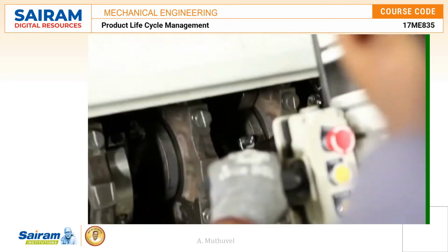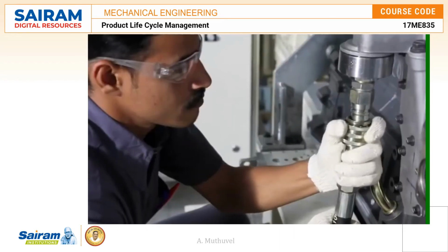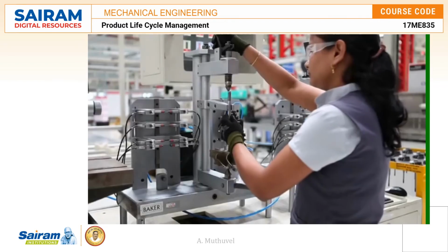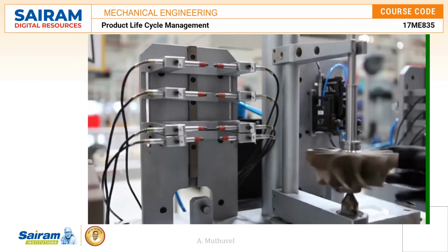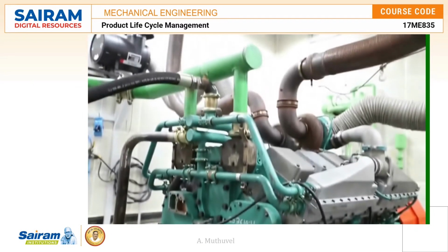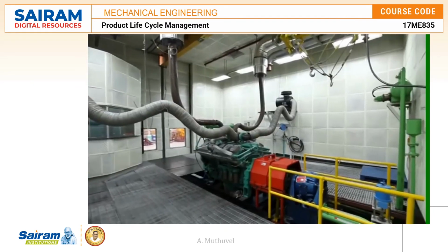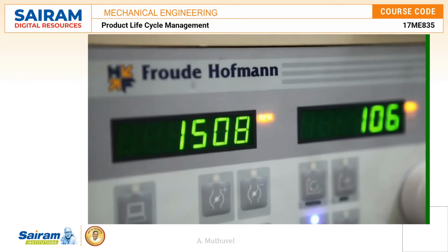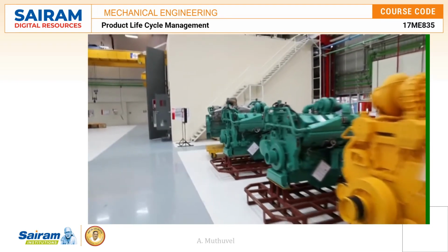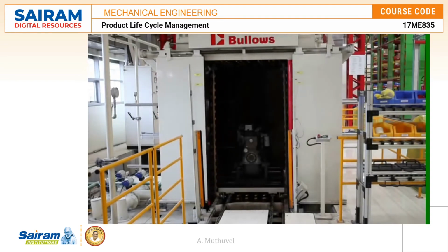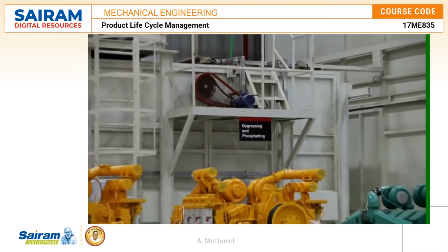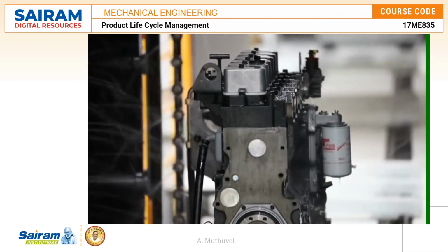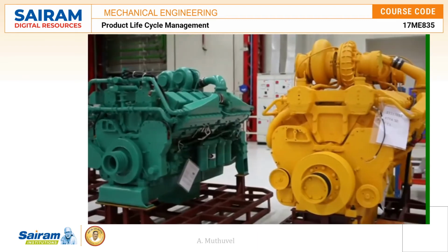Every component and engine undergoes countless hours in the test cell plus millions of hours in field testing to ensure reliability and durability. For instance, every remanufactured engine undergoes a testing cycle of 2 hours with varied loads that range from 25% to overload as per factory specifications, just like a new engine. After passing the comprehensive tests, the engine goes through degreasing and phosphating that protect the engine from rusting and corrosion. Using high-quality paints, the engines are given a brand new look.